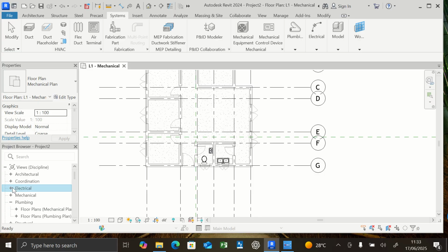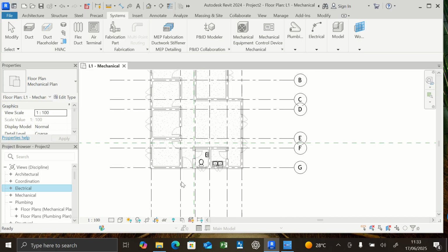So that is one of the advantages Revit gives us, especially when you are printing. When printing a particular system, you don't need to start turning off any layer because your template already takes care of that. This is primarily tied to the project template you started with while creating a Revit project.